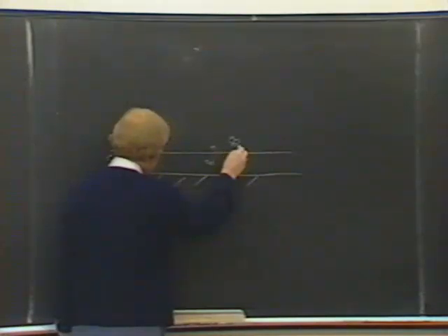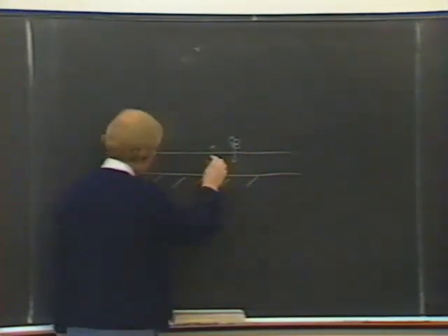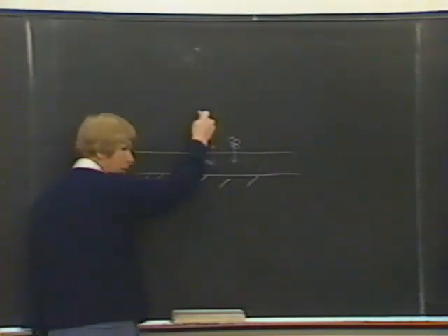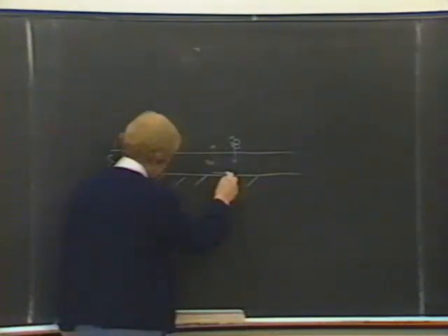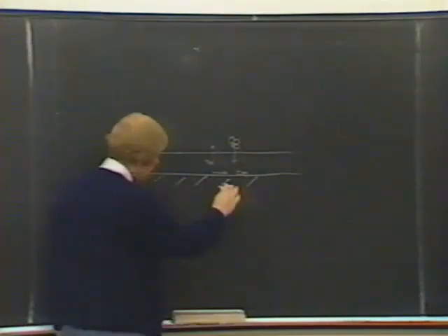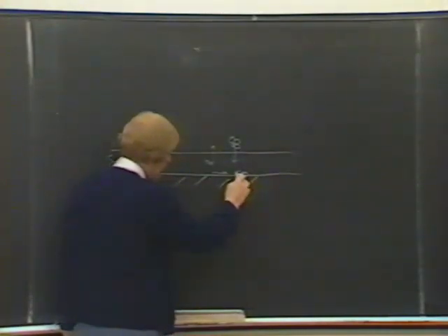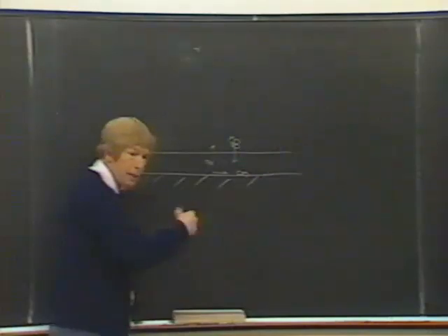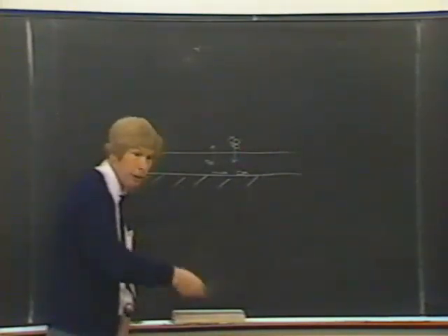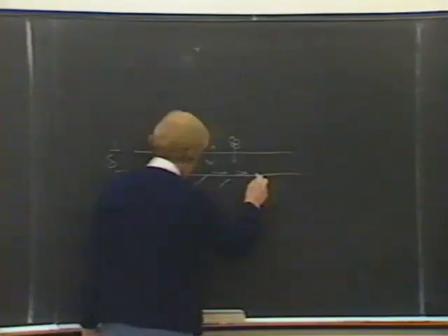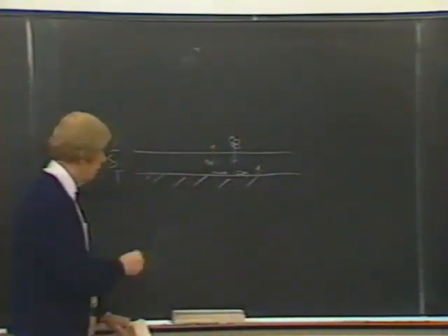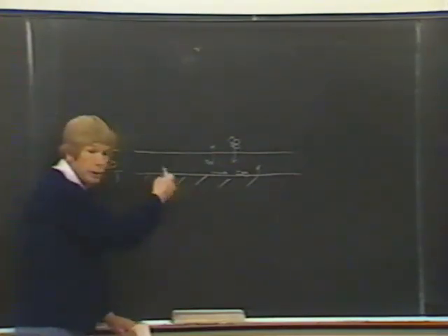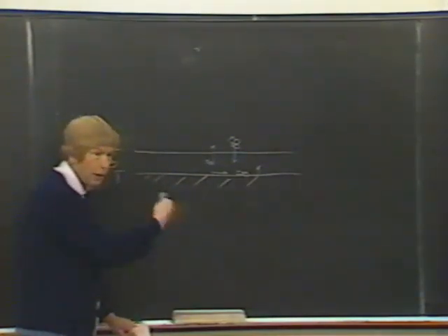I also said earlier that the particles that arrive at the bed may or may not stick, depending on the shear stress, and that if they don't stick, they either leave a portion of themselves on the surface of the bed or tear up some of the bed with them and are carried back up into this viscous layer. So you can see this is a region of a lot of activity. This is where the aggregation and disaggregation, this region near the bed, occurs in a simple open channel flow.